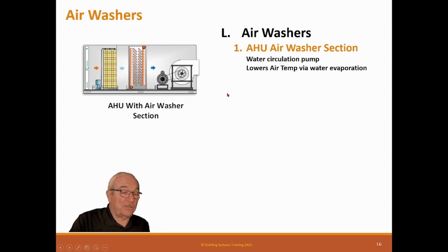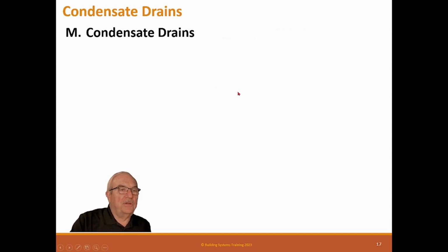What happens is the space gets confused because it makes it way too cold, and these are hard to modulate. They're really an off-on device, and by off-on I mean full-on and off. So it's hard to humidify with these if you have a really high altitude dry situation. These can work too well. Adds humidity to the air.